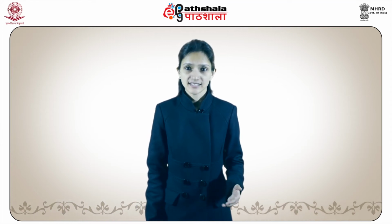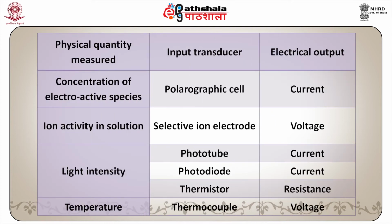If the measured property is not continuous, the detector can be designed to give pulse outputs, such as in high energy gamma radiation detectors. The quality and capabilities of the input transducer ultimately limit the overall performance of the instrument. We can see some input transducers.